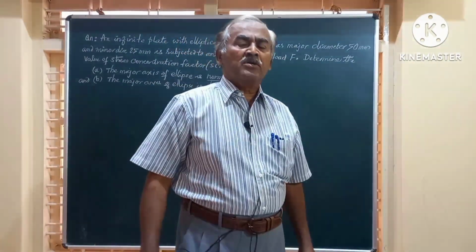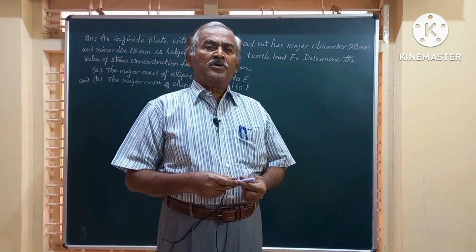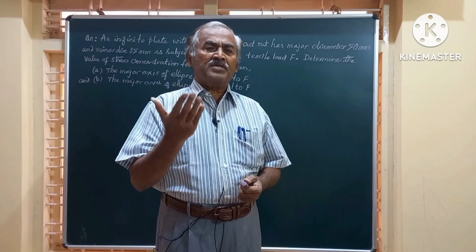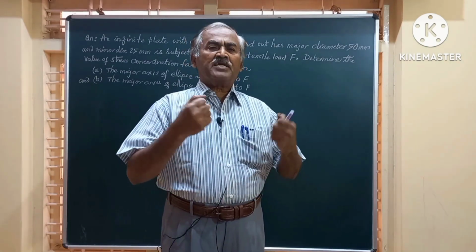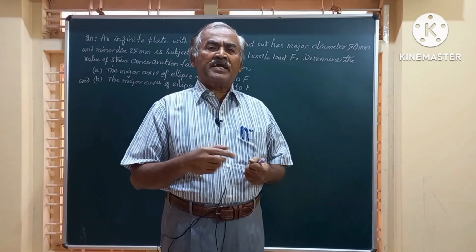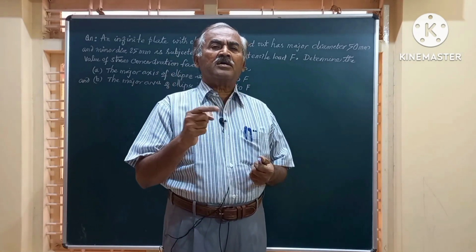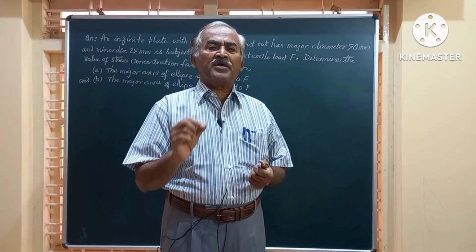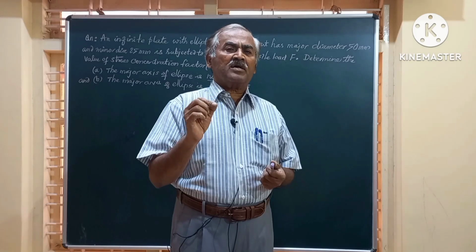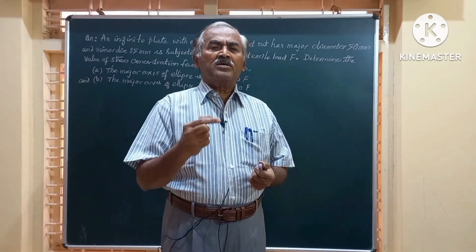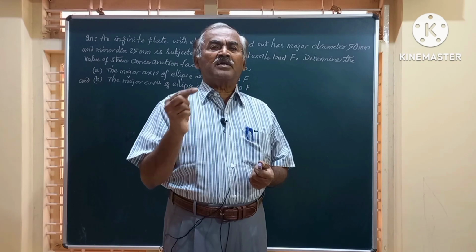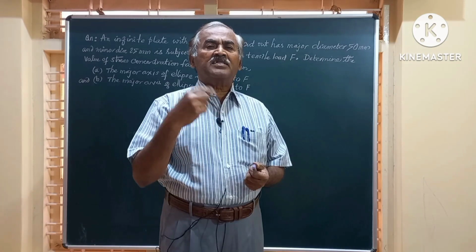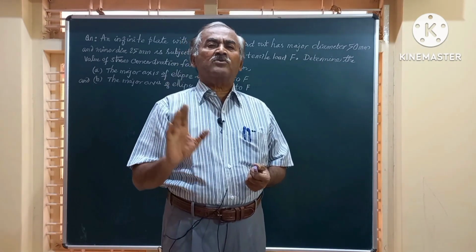In today's video, we have a numerical example on an infinite steel plate which is subjected to a pull, and this plate has an elliptical cutout whose dimensions are given, and we have been asked to find out what is the value of stress concentration factor when the major axis of the elliptical cutout is normal to the load axis, and in the second case when it is parallel to the load axis.